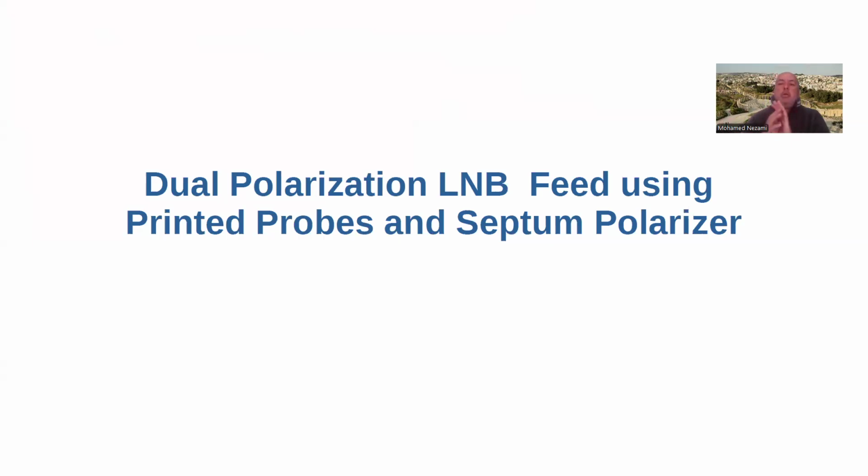As long as you're decomposing two orthogonal signals into separate paths, so that you can feed them to the LNB and bring them down from K, Ku, Ka band frequencies down to the L band, so that you can feed them to an indoor demodulator or modem or whatever.